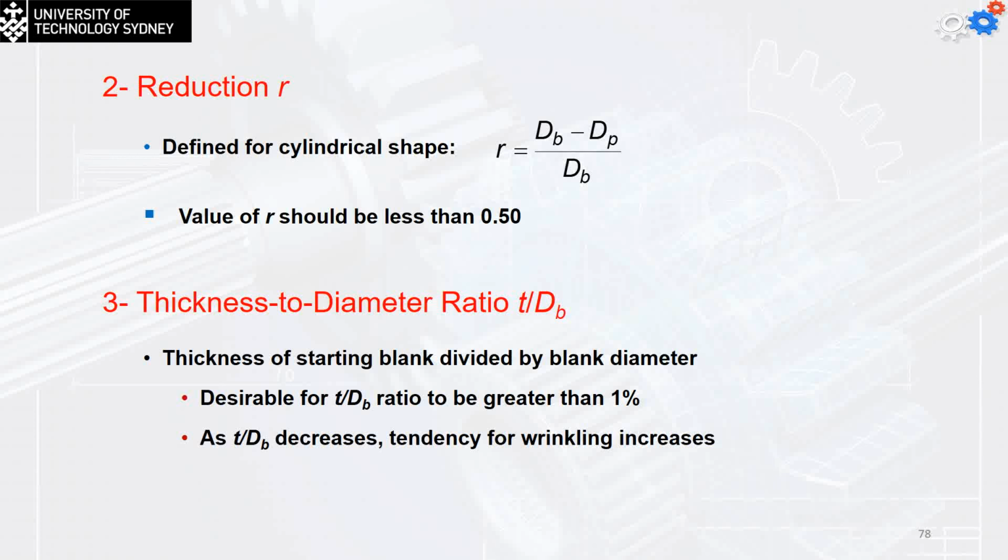Okay, so these are some of the shapes other than the cylindrical shape that can be made by the drawing operation. You can have the box shape, square ones, the stepped cups, the cones, the cups with a spherical rather than flat bottom, irregular curved forms, and actually, as I told you earlier, the car panels are made with the same operation.